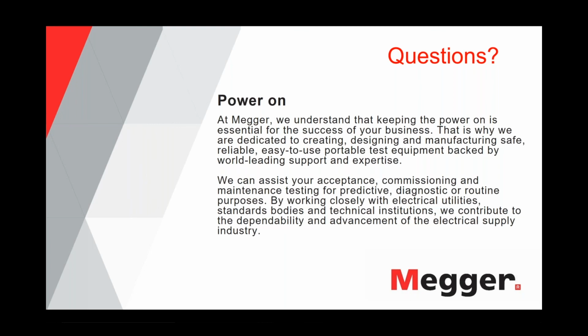Now, if the splice is really, really bad, it will have an influence. If the junction box is in a really, really bad condition, think about surface leakage, then it's the same as with a termination. If internally you have additional paths on surfaces where you can have additional creepage, then the tan delta value is always influenced.